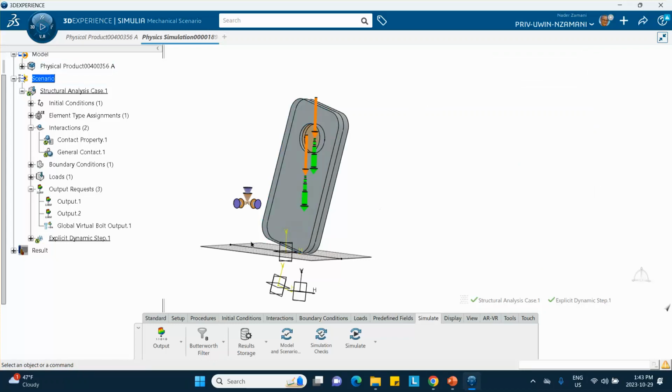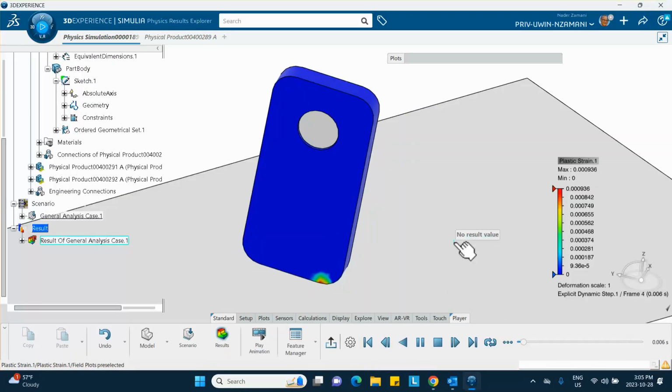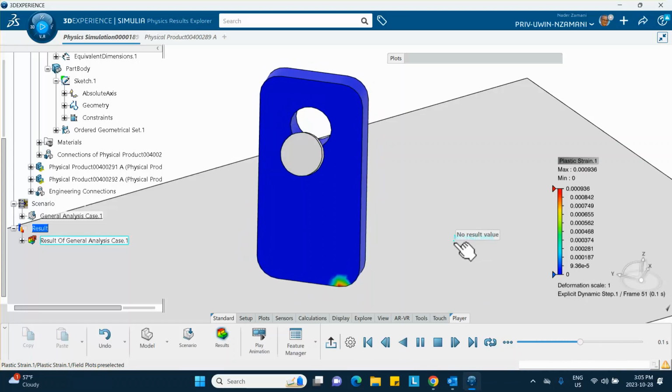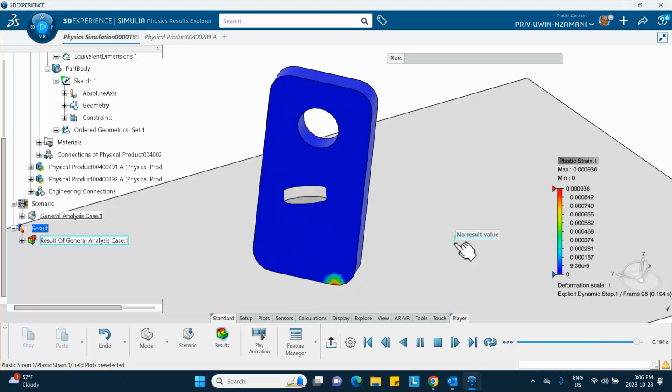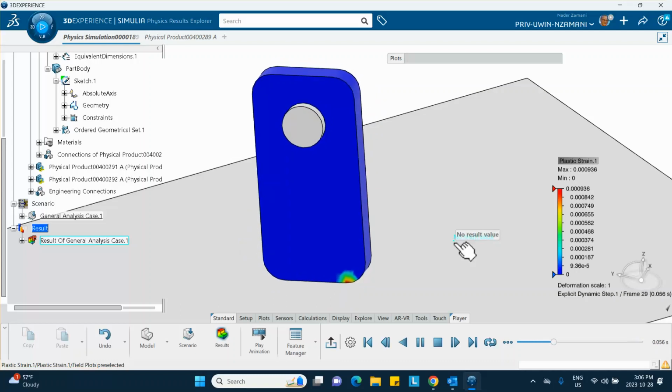All right. So I'm not going to run this thing, but I'll show you what the result of the run is once I took the friction out and tilted this thing a little bit. Okay, this is the video for the plastic strain in the two parts. The lens which slides out, there's no friction here, is made of an elastic material, and therefore it doesn't go into plastic mode, and you can see that it's all grayed out, okay? The biggest plastic strain is at the point of contact down below that you see.